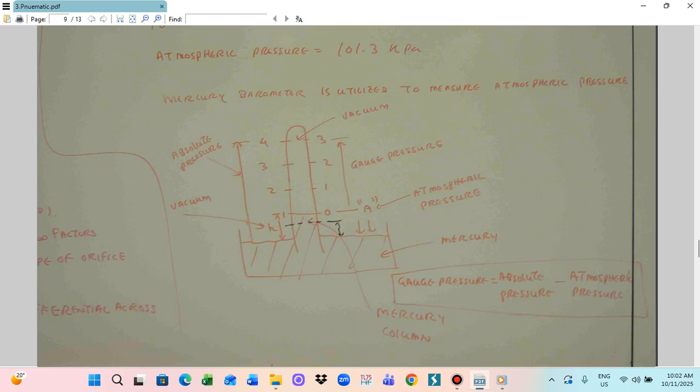Normally there is a compressor motor in the refrigerator. Those fellows cut the pipeline, open the compressor, take it out, rewind it, put it back, and solder again. After everything is finished, they have to recharge the refrigeration. What they do is bring a vacuum pump, so that all the air in the refrigerator pipeline is taken out. In this way we use it as a vacuum gauge.